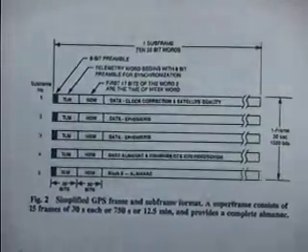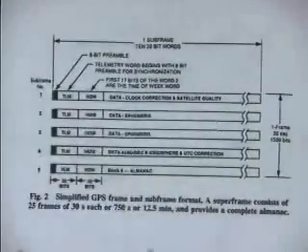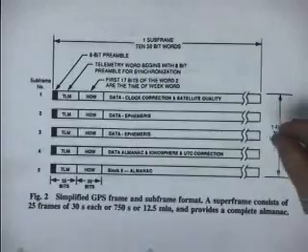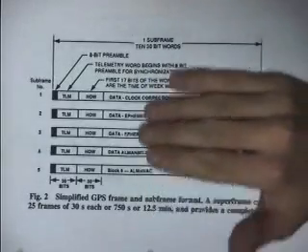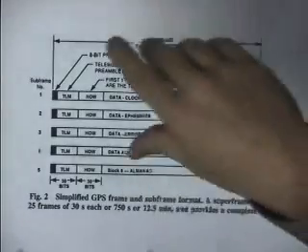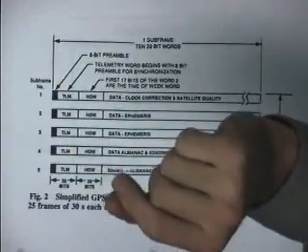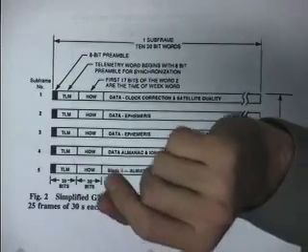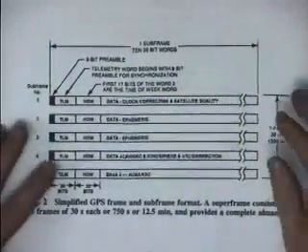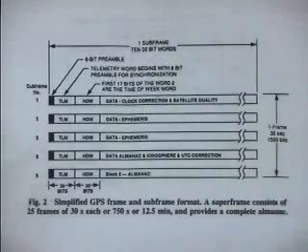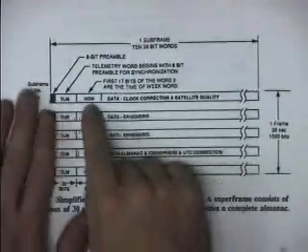This is a plot of the data structure of a waveform that's actually riding on top of the spread spectrum down to Earth from each GPS satellite. It's a very slow waveform. It's only 50 bits per second. But there's not really a lot of need for throughput on that waveform because it's really just supplementary information to help a receiver decode the signal.